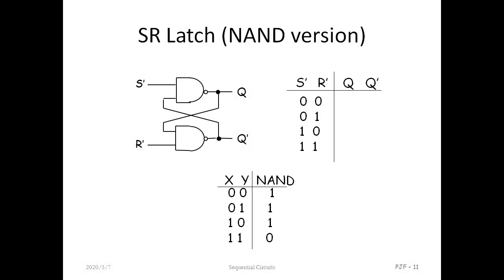Now these are the SR latch. What is a latch? I will define the latch in my next slide, but I will also explain it now. A latch basically checks all the input values and correspondingly changes the output when enabled. For example, SR latch, let us understand case by case.